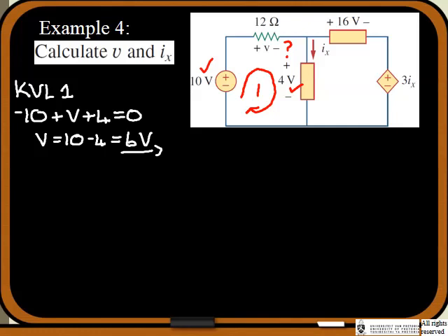Next we need to solve for Ix. Now this is a little bit hidden, because initially you would think that you need to solve for a current. It's a current that we're looking for, so do we need to use Kirchhoff's current law? Well, we don't know what the current is into this node. We know what the current is from there, so that's not going to work.